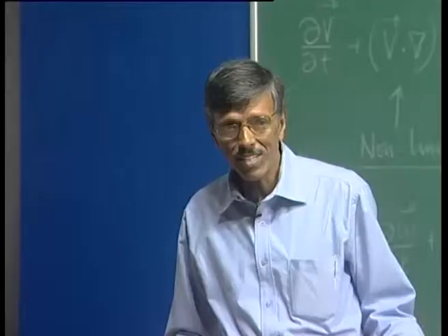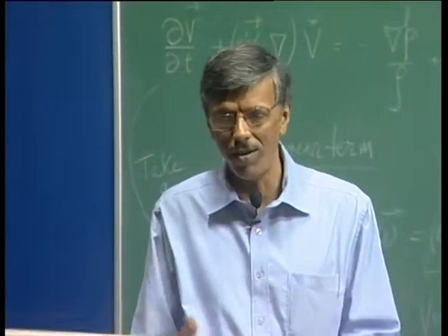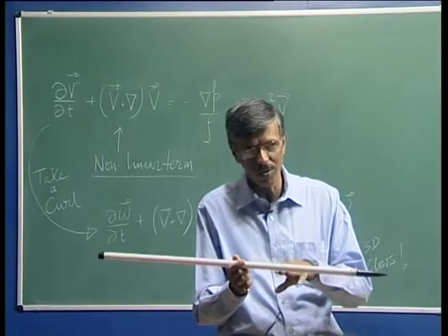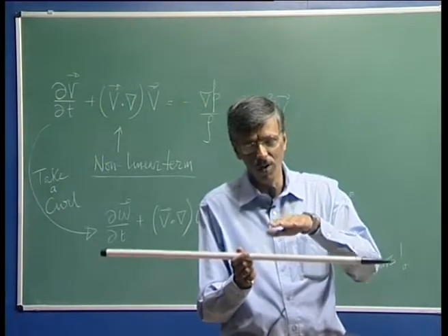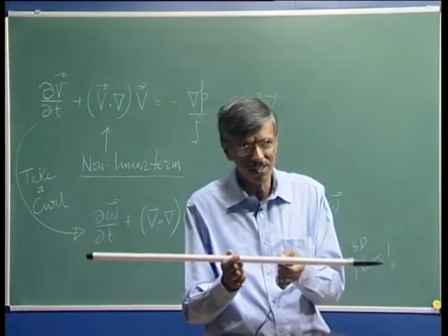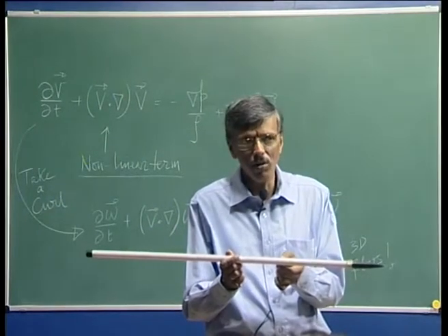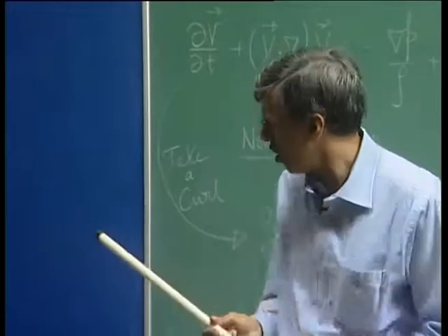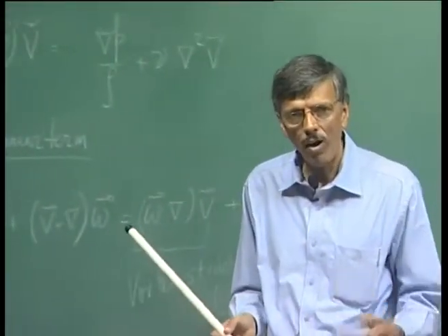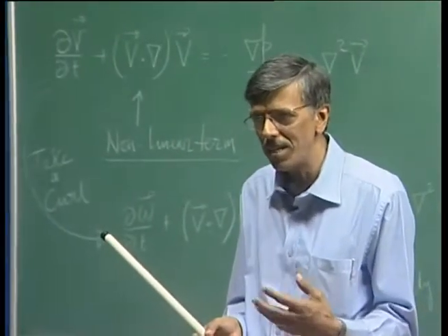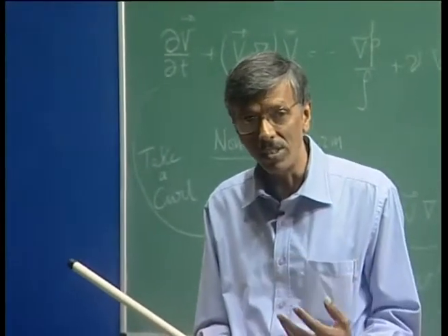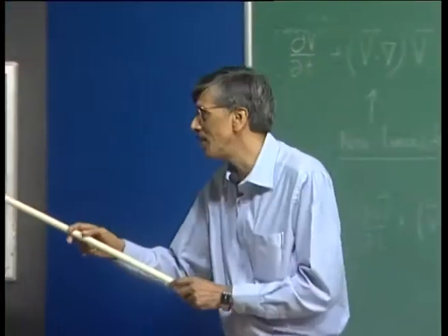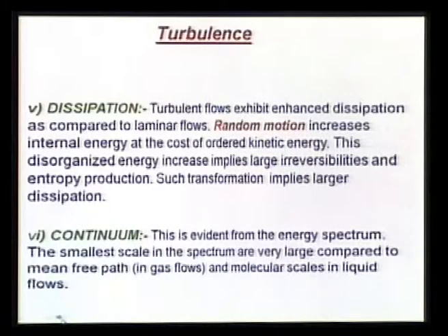Physically, trying to understand what happens, if I have a laminar flow, I will have a thinner shear layer. So this transition from a no slip wall to the fully developed flow is occurring over a thinner section. However, if I now set in motion turbulence, what will happen? This will become thicker. How do I do it? I just create a very strong motion in a macroscopic scale, which is random. That is what we talked about. Turbulence is randomness in a macroscopic scale.